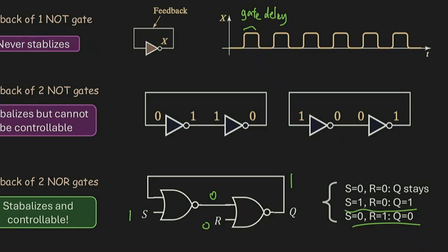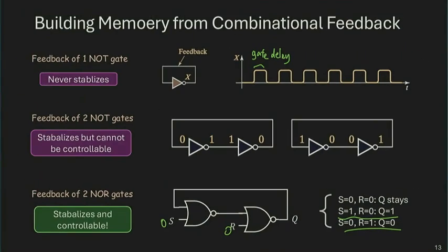And now if you set both of them to 0, we essentially get back to that previous scenario. You have two inverters back to back. 0 converts a NOR gate into an inverter. So you have that two inverter picture. So data gets to be stabilized based on the previous condition and remains in that device even after we have spent many seconds or many nanoseconds, let it run. It will remain at the previous value.